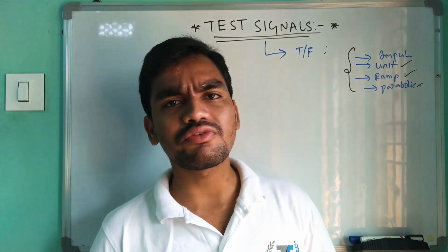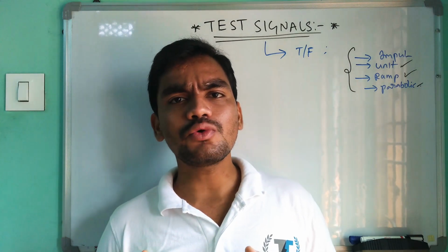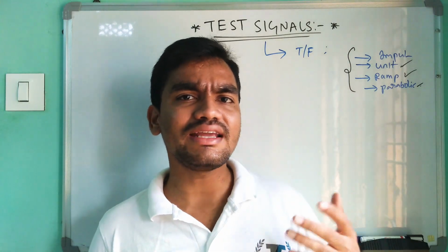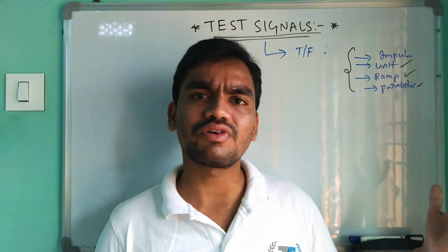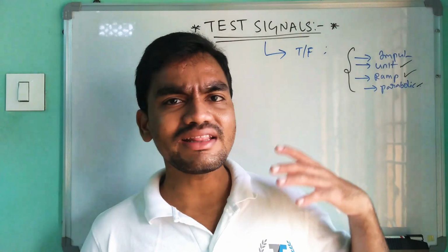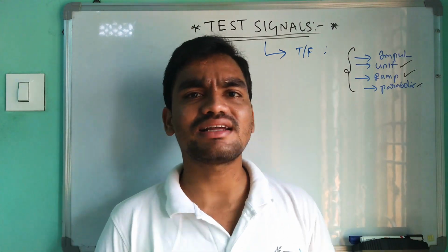Before going to the video, what exactly does a test signal mean? If you apply an input to the system, and suppose TF is the transfer function of the system, then you obtain the output of the system. The inputs that are applied to the system to obtain the transfer function or the output of the system can be called test signals.